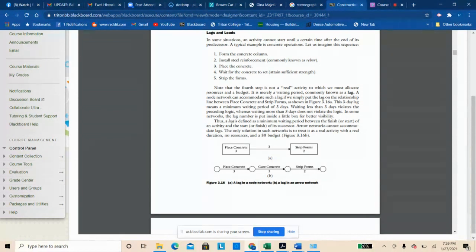You don't do that, somebody cracks the concrete, then you hear about it. And if the concrete's a necessary component, if it's holding up structural steel or something like that, they will actually do concrete core testing, where they come out and make sure, all right, I'm supposed to have 2,800 pound compressive strength concrete.